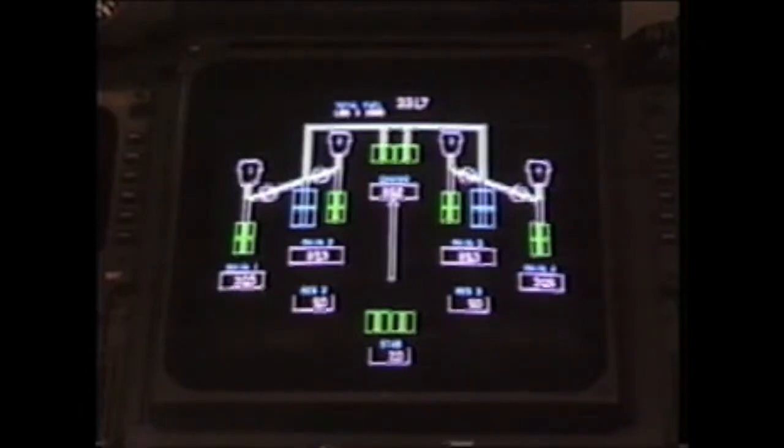Note that the stabilizer pumps are now green, indicating the pumps are actually running, putting out pressure. Note the transfer arrow from the stabilizer tank to the center wing tank, indicating that stabilizer transfer is occurring. This will happen automatically, regardless of whether the fuel synoptic is displayed.